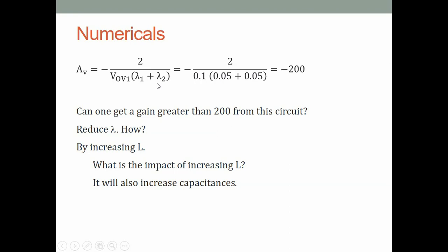for digital circuits, because digital circuits work faster when the channel length is smaller, because dimensions are smaller, the resistances are smaller, the capacitances are smaller, so they work faster. Because the transistors are smaller, you can put many more transistors on a chip, and therefore the amount of system one can build on a chip becomes larger and larger.